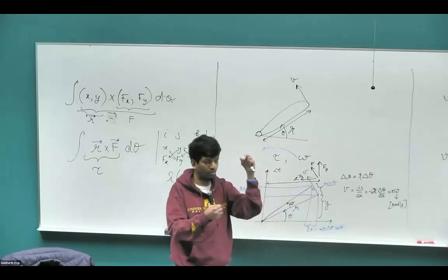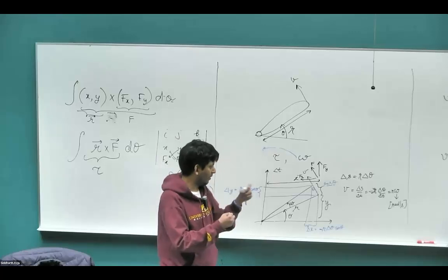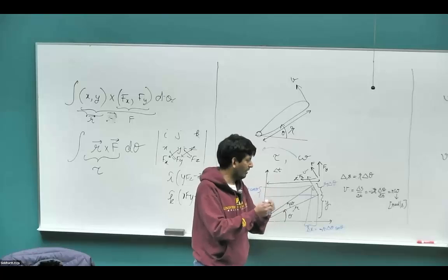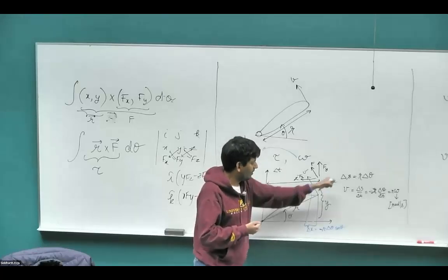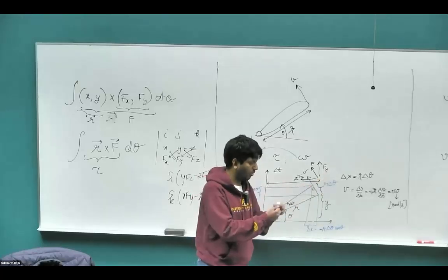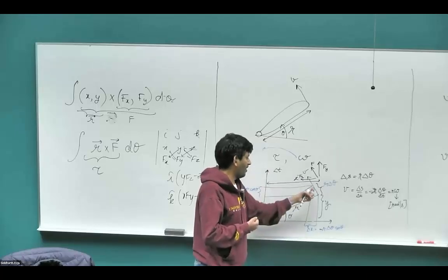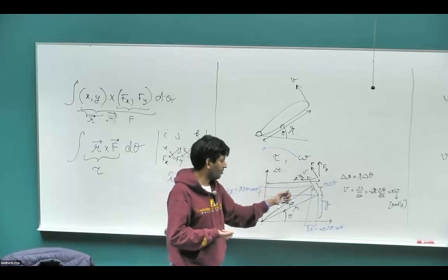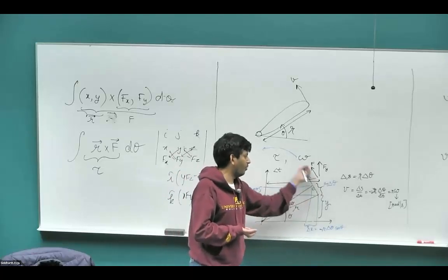That's why in the motor there are things called retaining sleeves, because when the rotor rotates, you don't want the windings to come out due to centrifugal forces, as well as to retain the conductors from moving when there is a force pulling them outwards or compressing them inwards. But that is not a component we are interested in analyzing. In this course, we are only interested in the component that would actually rotate the motor.